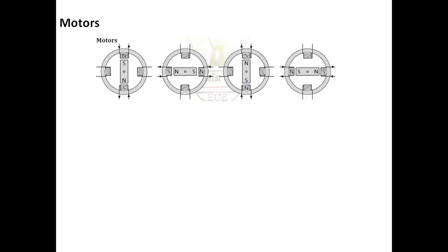Okay. So along with the position sensor, to have control over the position, we can also make use of a servo controller circuit that compares the actual and the desired positions. That will give us a driving voltage for the motor that depends on the difference between the positions.